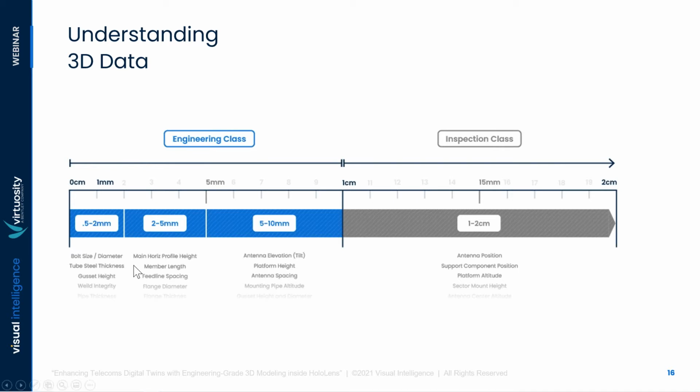If you're coming away from that and you're looking at widths or standard angle sections, they're coming in 10mm separations or whatever that is in imperial. So you could get away with centimetre at that point, but if you need to know the thickness of the member, which could constitute 20 to 40% structural capacity difference, you really need the engineering class data. And happy to have chats about how and why that's important.